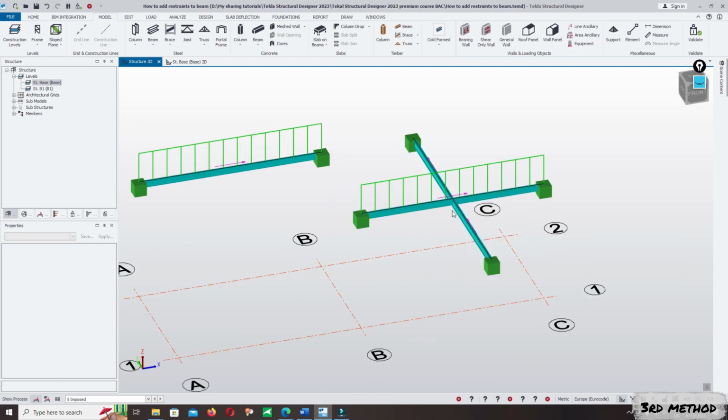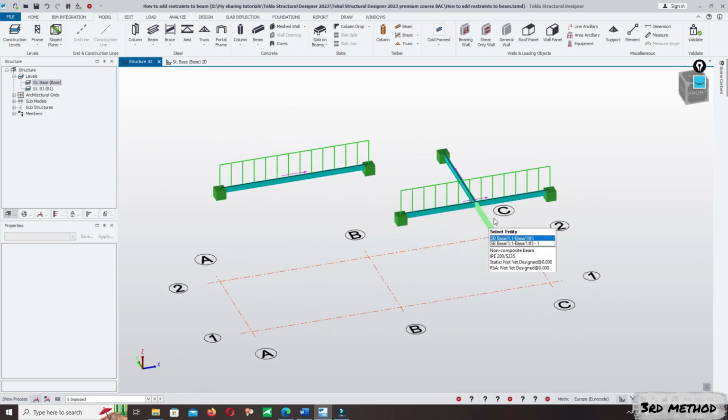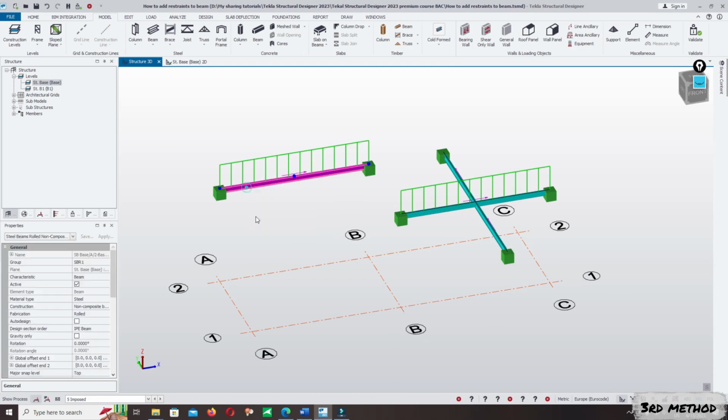There are two sub beams that intersect the main beam at lengths of 0 meter, 3 meter and 6 meter, at the center of the main beam. So it's similar to this beam when you model a beam without a sub beam, but you can edit the option during modeling to correct the lateral torsional buckling factor on the main beam.